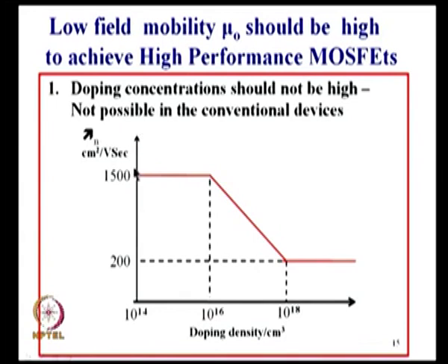increase the mobility or limit the mobility? If you plot mobility mu n, this is actually mu, it does not show here, this arrow is mu, I think because of a change in the program. The mobility is on the y axis and the doping concentration on the x axis. If you recall, to reduce the short channel effects, we always increase the doping in the conventional MOSFET.